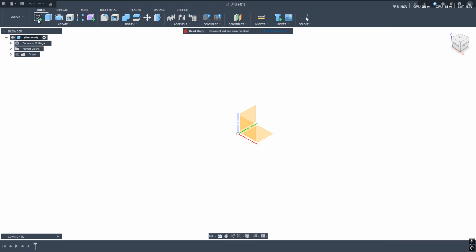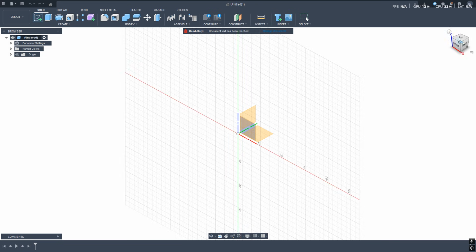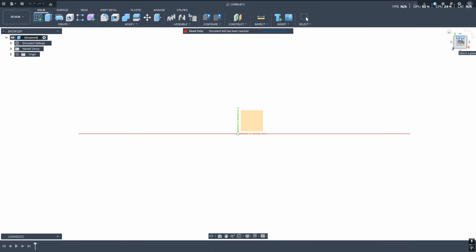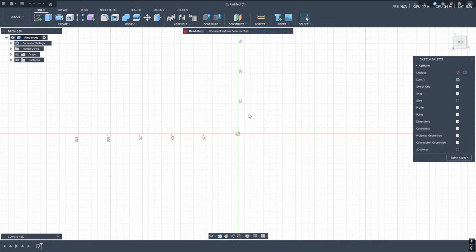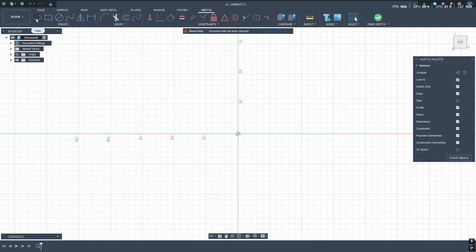The simplest way, you click the sketch, and I would always click here on the top to make sure I design my cutter on the top view of the sketch. So from here, if I click this, I will get a few options up here.